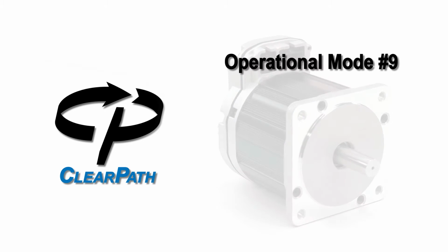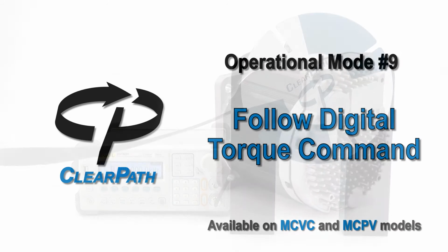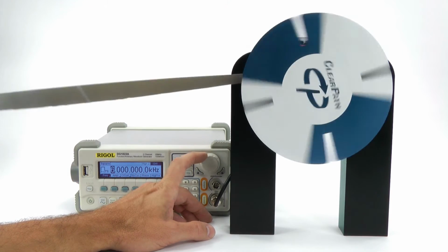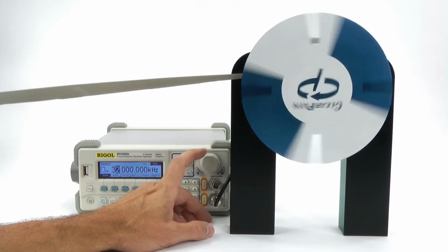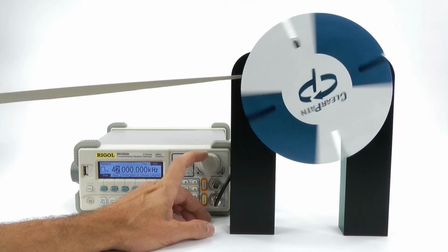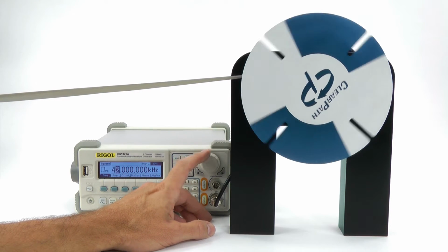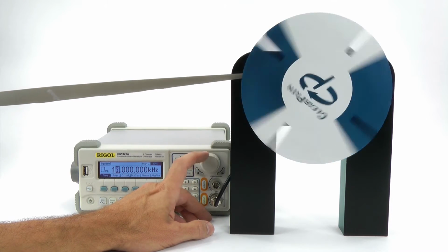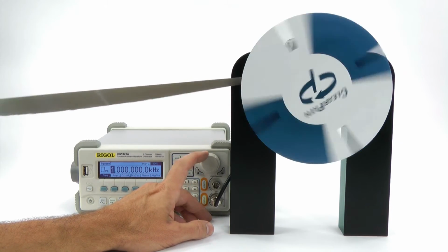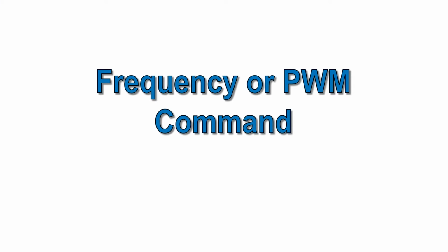ClearPath Operational Mode 9. Follow Digital Torque Command. The Follow Digital Torque Command is the mode to use when you need to programmatically control motor torque rather than speed or position. To use this mode, you supply a frequency or PWM command signal that is proportional to your desired torque.